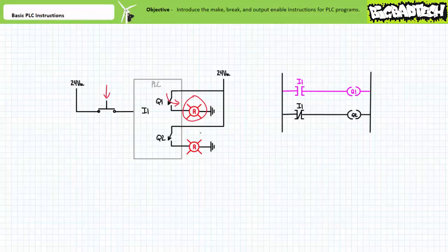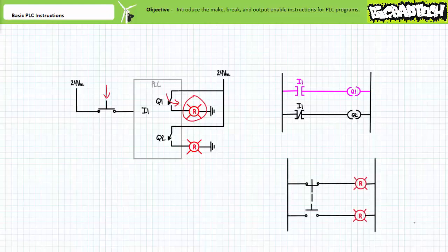Do you see what this simple PLC program has already enabled us to do? We saved money. If we wanted to implement this same function using traditional hardwire relay-based ladder logic, it would necessitate more wires in addition to a more expensive and bulky mechanically interlocked switch package with a set of normally open and normally closed terminals. Note, as implemented using this flexible PLC, the field input device requires only a single set of terminals and contains fewer wires.